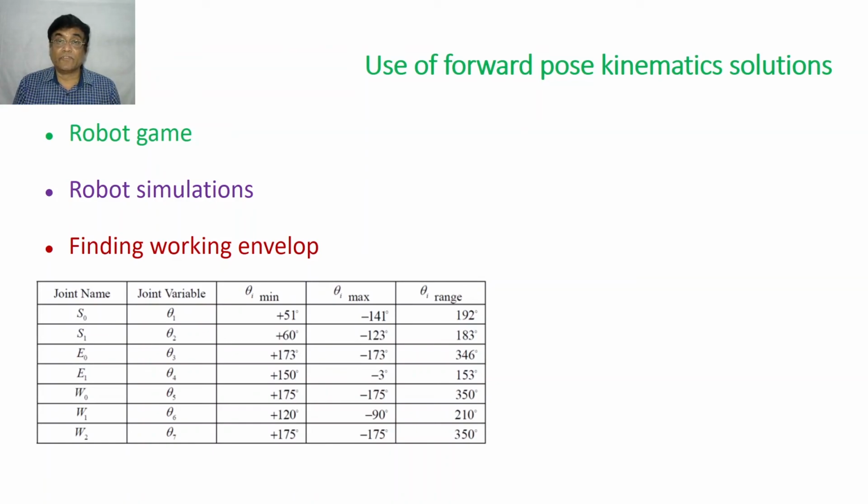But wait a minute, there is no free lunch. This forward kinematics is not at all complete modeling, because many pieces of information are not there. The fundamental one: if I want a robot to follow a trajectory, forward kinematics will not be able to do it unless you use teach pendant mode. Industry people use it, it's very easy, but as a roboticist, you should know how a robot can follow a trajectory.